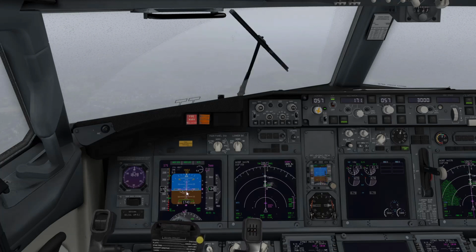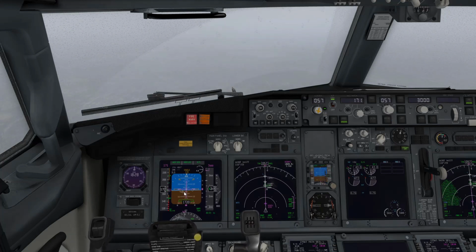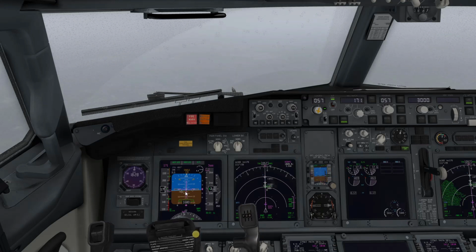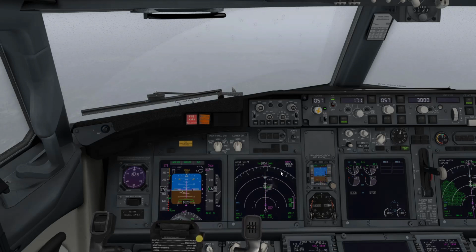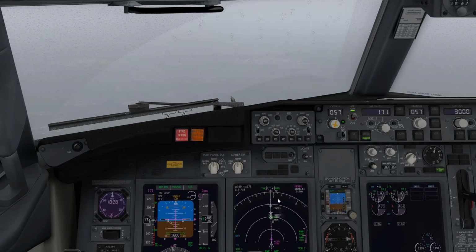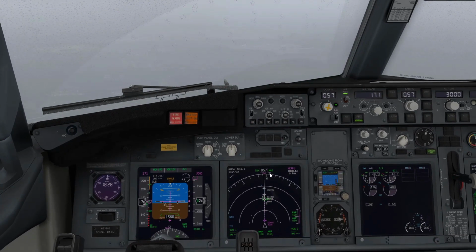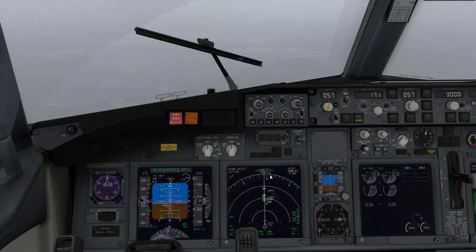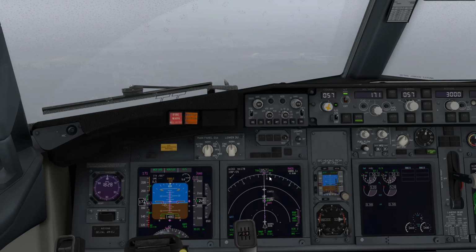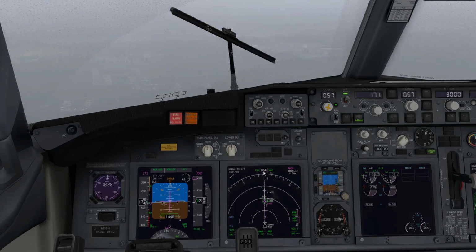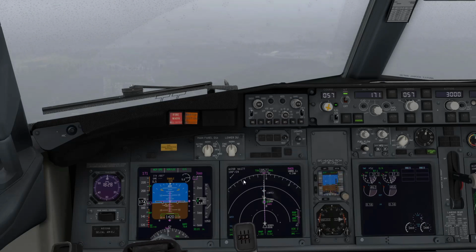So we're drifting a little bit. We've got our aircraft turned a little bit to the right, and that makes sense for a crosswind to the right. This shows us our heading. So our heading looks like approximately 063 degrees, and our track is 057 degrees.